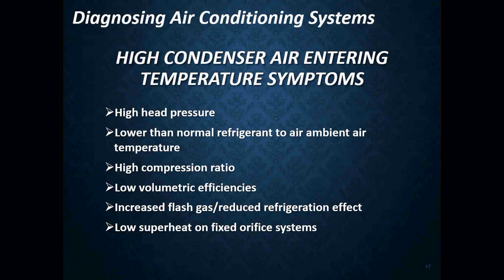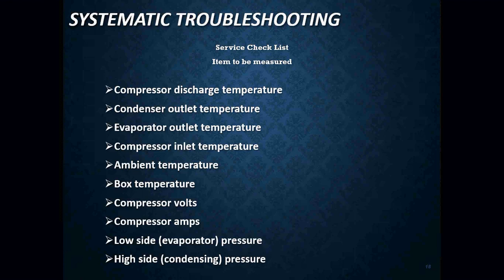However, heat rejection on a higher condensing temperature will force the system to have higher compression ratios and therefore lower the efficiency of that type of system.